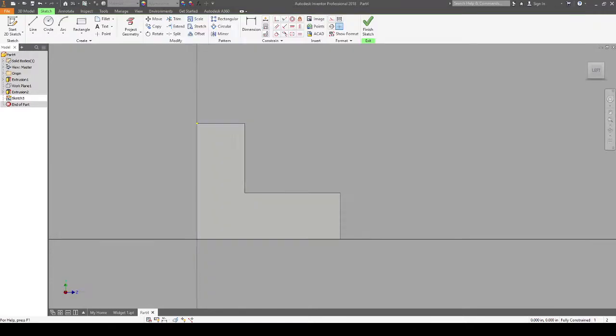Okay. So going back to Inventor, this will be the long side of the triangle. So clicking on our line tool, we're going to start here at the bottom, and then we're going to go up 0.75. That'll go all the way up. And then here, we're going to go out 0.5. And then we're going to connect those to close off our triangle. Click Finish Sketch.